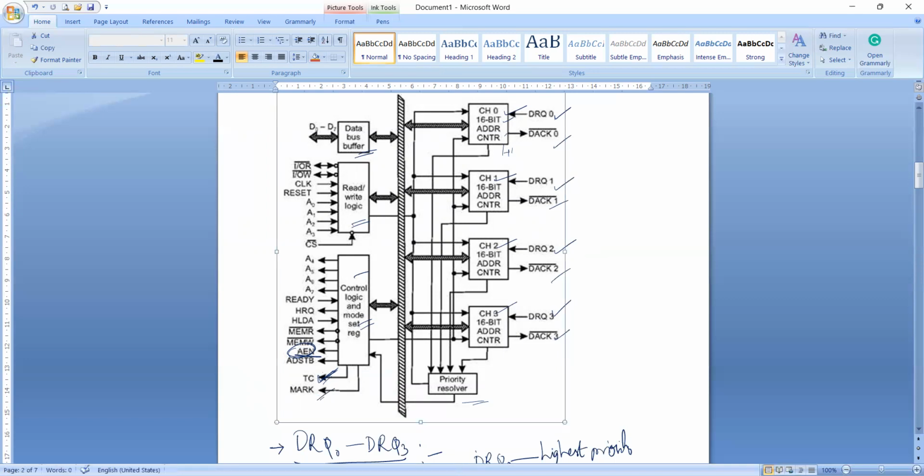And next one is the MARK signal. This MARK will be activated after each 128 cycles, or integral multiples of 128, from its beginning. Then it indicates the current DMA cycle is the 128th cycle since the previous MARK output to the selected peripheral devices. And next one is VCC. This VCC is a supply line, which is required for the operation to be secure.